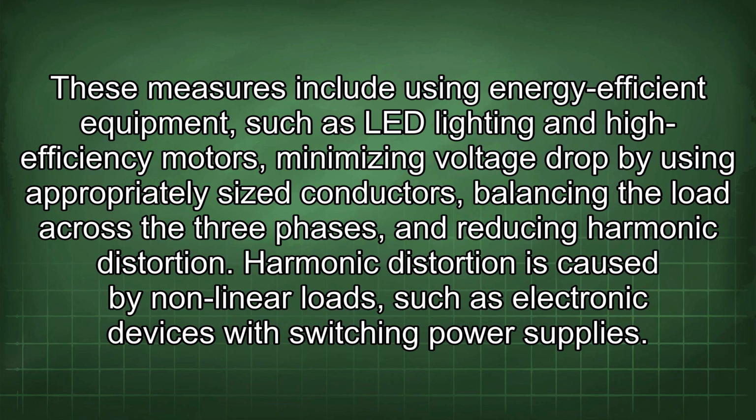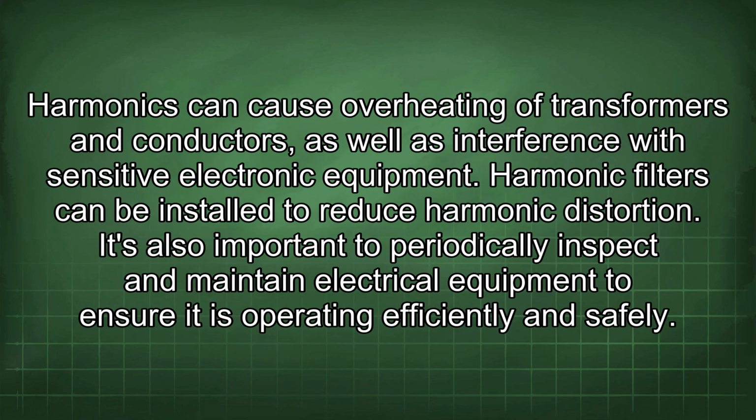Harmonic distortion is caused by nonlinear loads, such as electronic devices with switching power supplies. Harmonics can cause overheating of transformers and conductors, as well as interference with sensitive electronic equipment. Harmonic filters can be installed to reduce harmonic distortion.